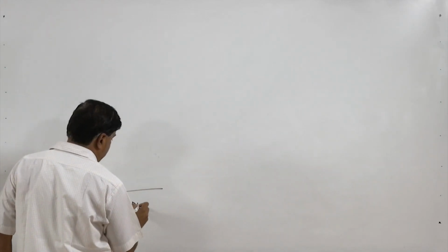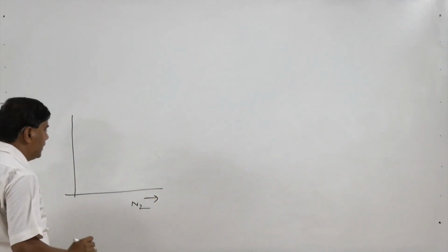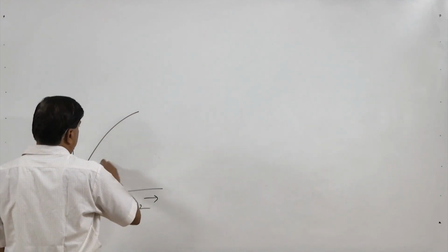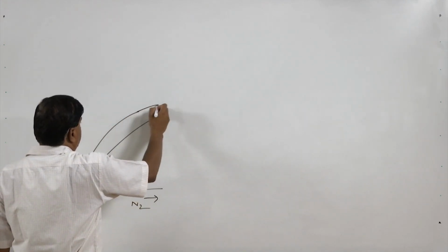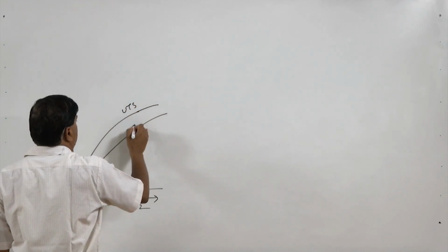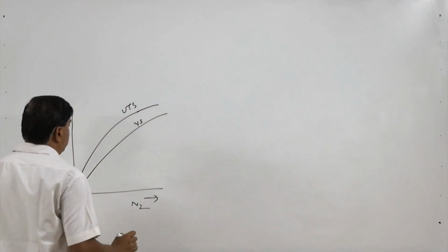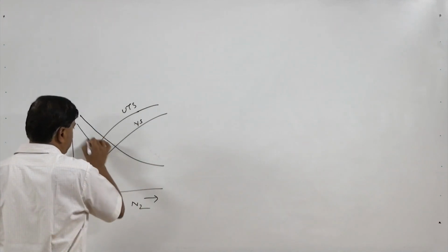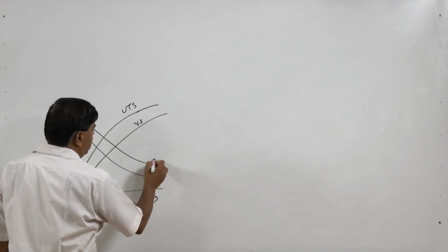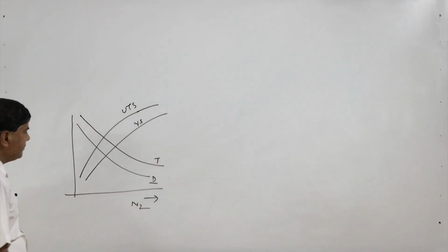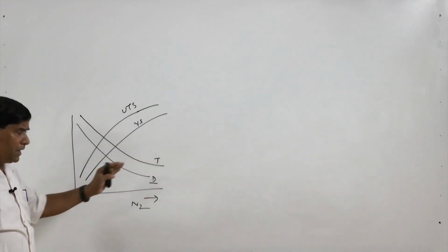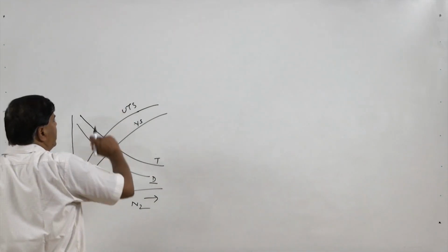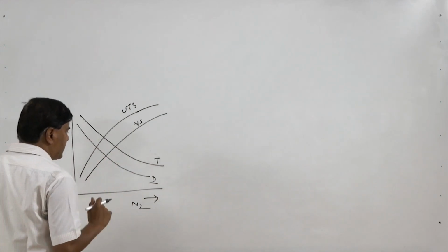Here, increasing concentration of nitrogen in the weld in general increases the strength, yield strength and ultimate strength, like UTS and yield strength, but it happens at the cost of ductility and toughness. So, ductility and toughness in general decrease with the increase in nitrogen concentration in the weld, while yield strength and ultimate strength increase.